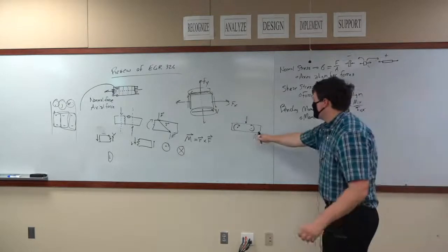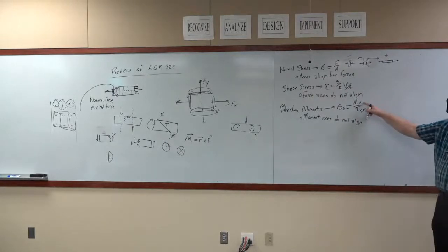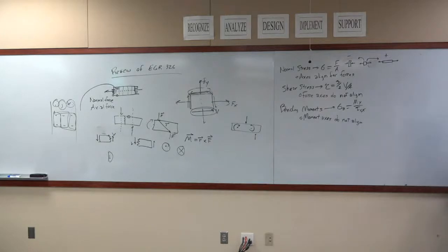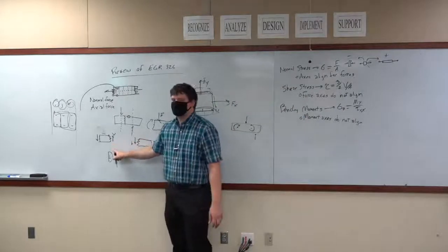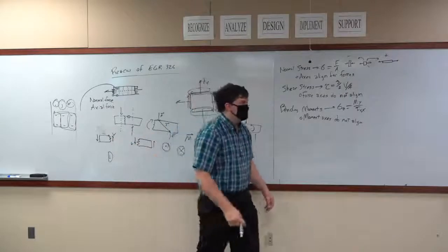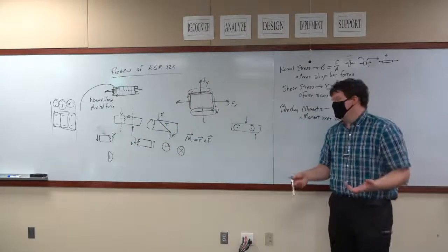Okay, so if I'm looking at this distribution, this y that's being put in here means that the stress varies across the cross section. Just like what we talked about over here, where the stress varies across the cross section for the shear force, with the maximum value right in the middle, the stress varies across the cross section also for a bending load.